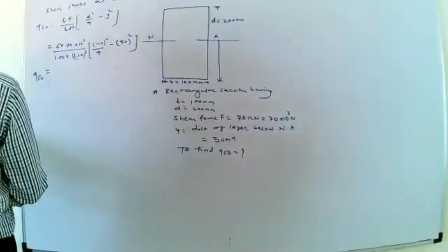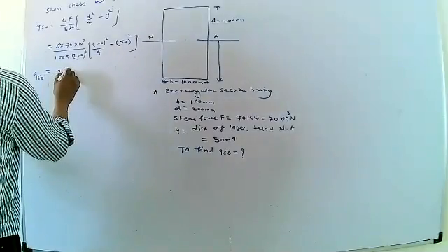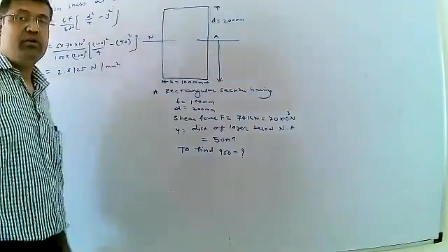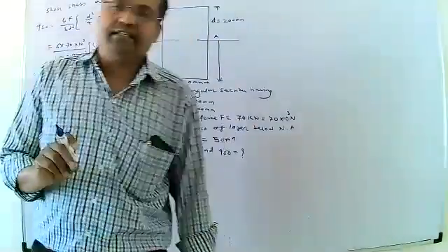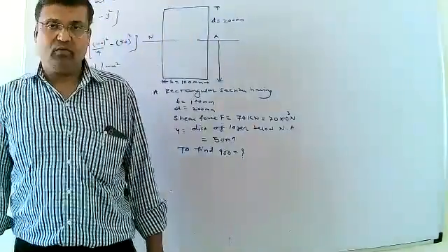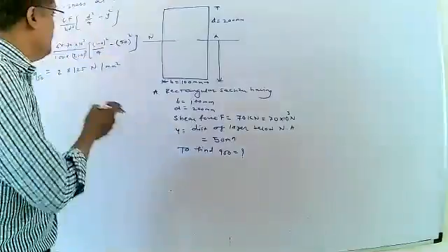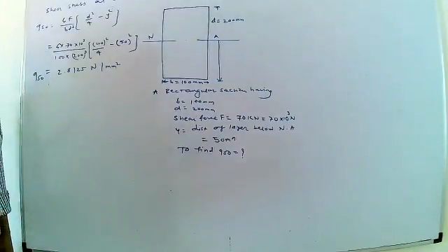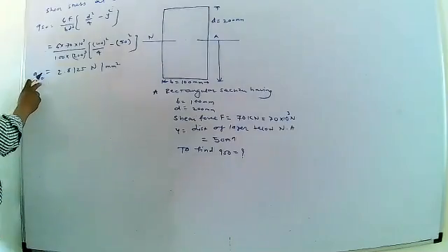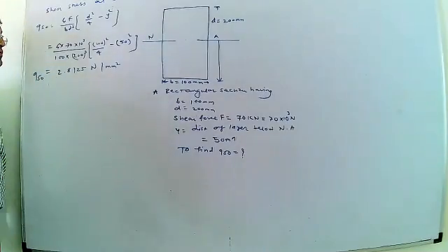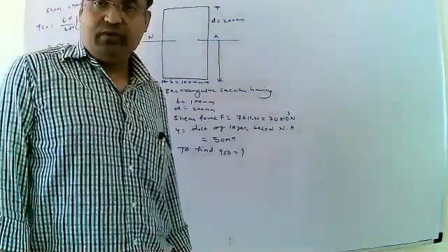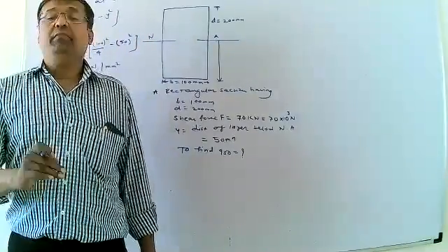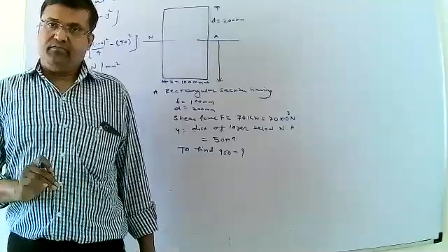Q50 is equal to 2.8125 Newton per mm square. That is the unit for shear stress; the unit of shear stress is Newton per mm square. After you do the calculation and simplification, we get the final value q50 equal to 2.8125 Newton per mm square. That is the value of shear stress at a distance of 50 mm below the neutral axis.